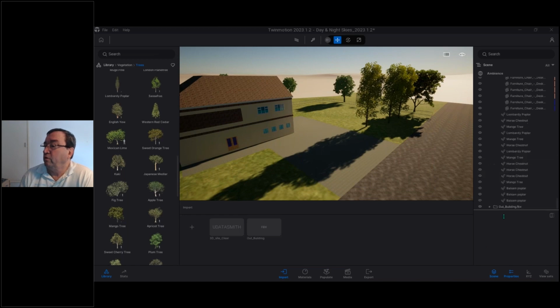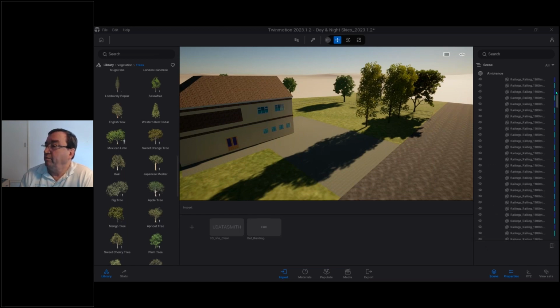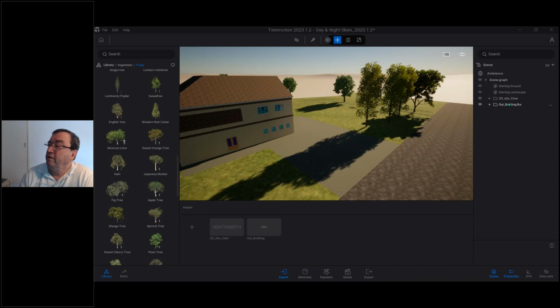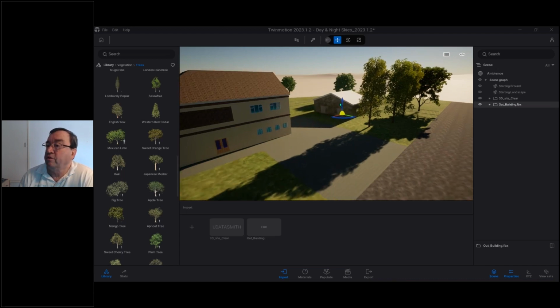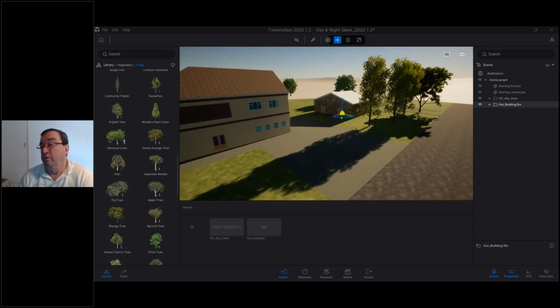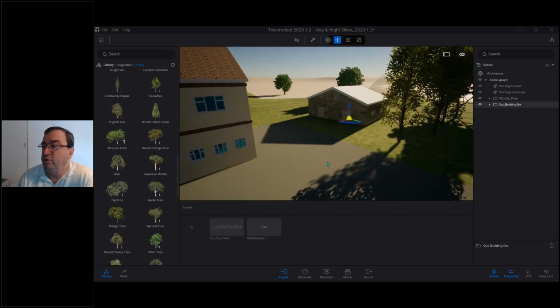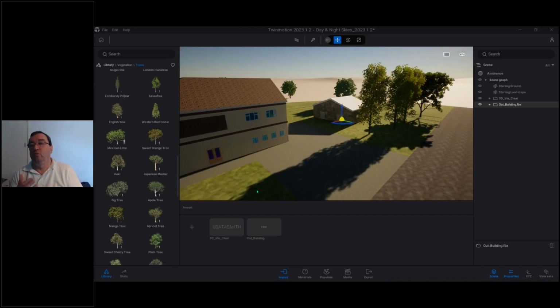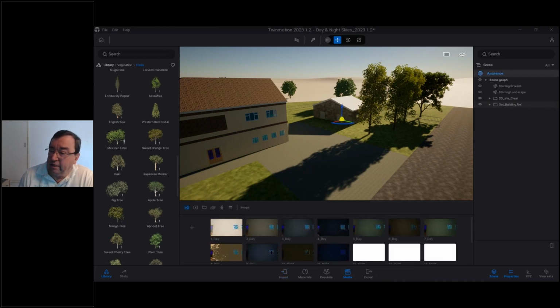If I come all the way up here, collapsing all this a little bit, there's my outbuilding. And then I can bring that into position and put it where it's got to go. So like I said, I'm using not only my Revit geometry, but also my 3D Studio Max geometry in here. The idea now is that I can continue to bring in the other phases if we wish, and we would do that through this little media tab over here.